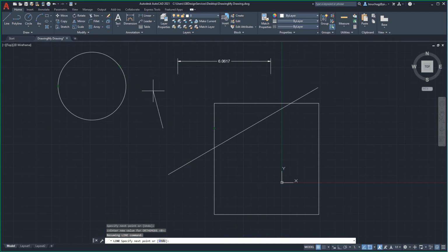A helpful tip to remember is that our drawing environment can often get a little crowded, making it difficult to get the software and the cursor to recognize the Object Snap point we are seeking to reference. By typing the first 3 letters of the Object Snap name, we'll isolate the chosen snap point style, ignoring all others. We'll examine an instance of this in our next video.